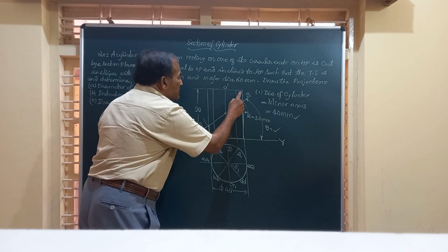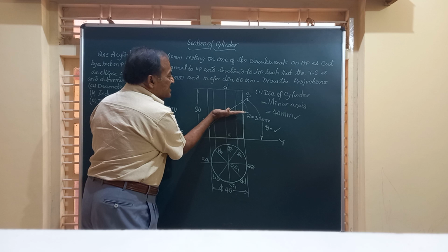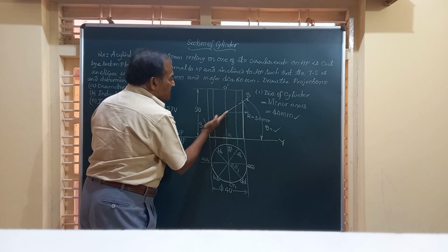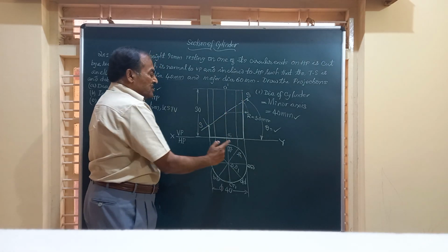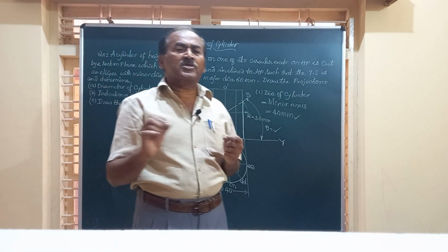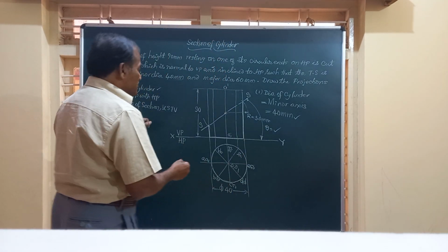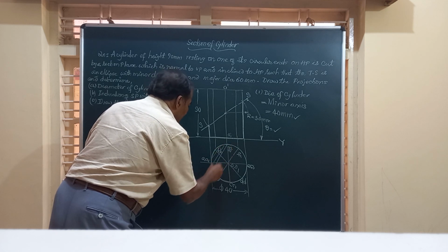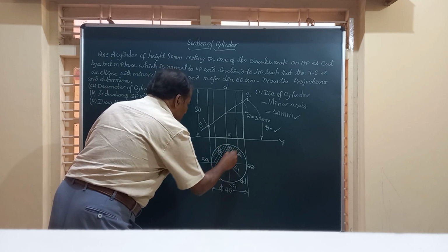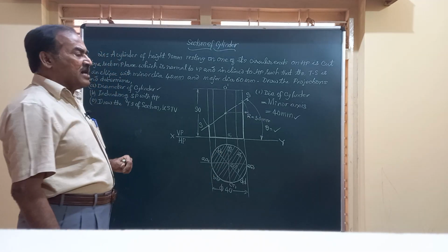If it is cut anywhere between this end and this end, either by a horizontal section plane or by a section plane inclined at any angle between these two limits, the whole or complete top view of this solid is to be shown hatched. So, if it is a circle or cylinder, we are going to hatch or section the complete top view by lines inclined at 45 degrees to the horizontal.